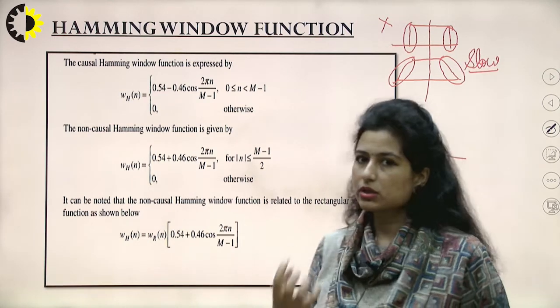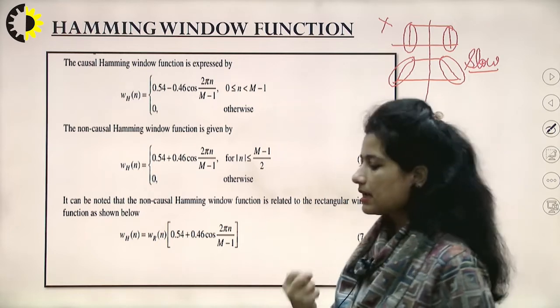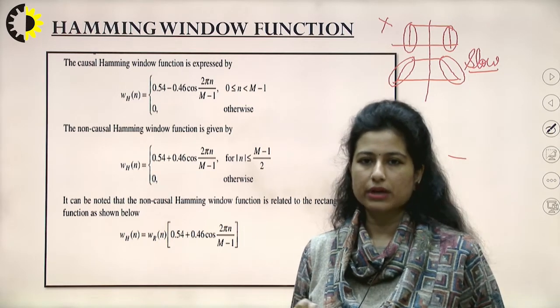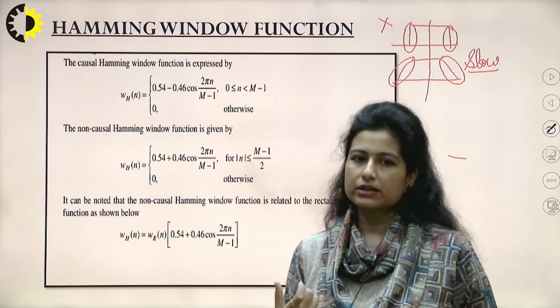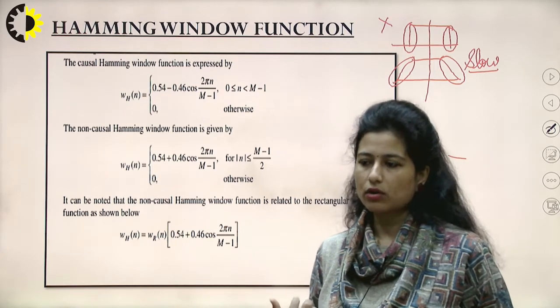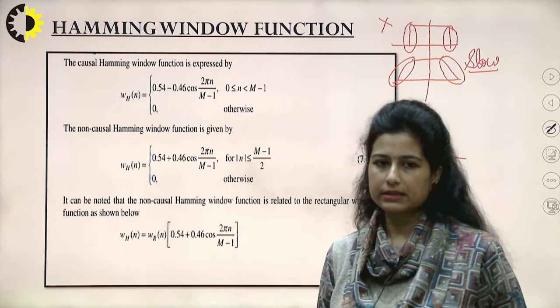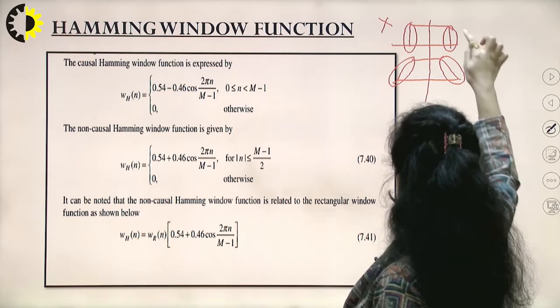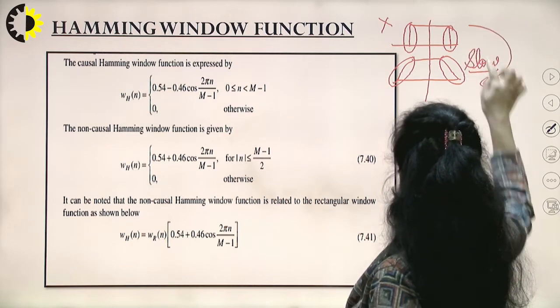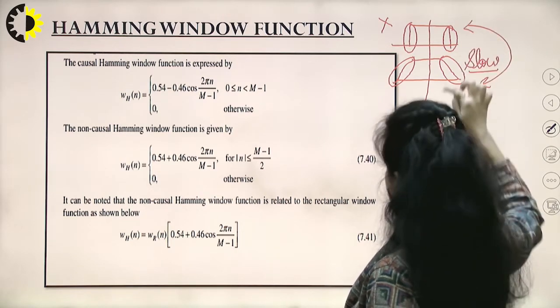The greater the slope of this curve, the fewer the oscillations or ringing effects. But the larger the transition band, the more energy is wasted in the side lobes, meaning more energy is present in the stop band. Again, that is not desired. So we have to make a certain compromise between these two.